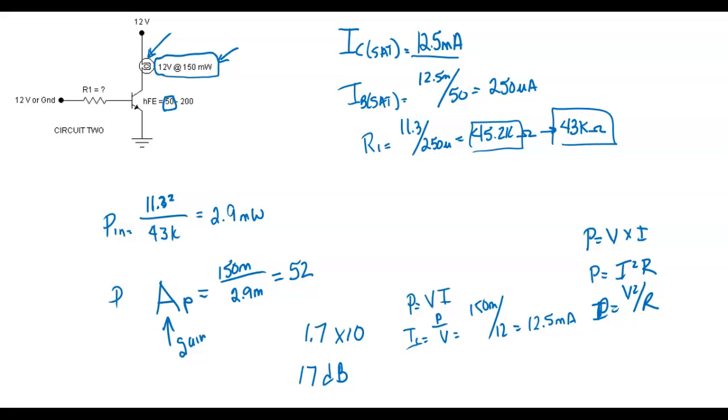So if I saw 17 dB, what would the gain be? Well, I would just move the decimal point to the left and raise 10 to the 1.7 power, and that would tell me the actual gain. So we use dB kind of like we use engineering notation. It allows us to round. We'll usually round to no more than one decimal point, and we round once we convert it to dB. So it's not extremely accurate, but it's accurate enough. That thing's got a 17 dB gain right there.